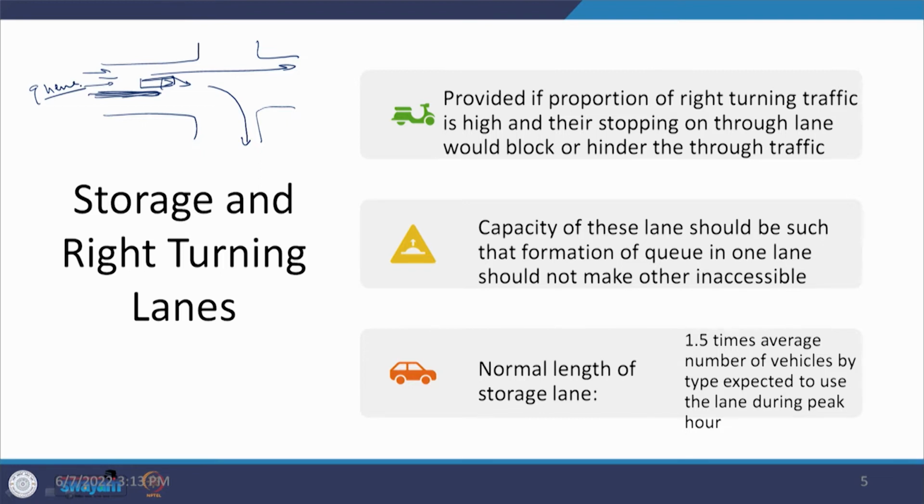and this is not good for the efficiency of this particular intersection. And this is the reason we need to look at what should be done so that this right turning traffic, when it stops here looking for an opportunity, because there is traffic coming in this direction also, does not create an impact here in terms of a conflict point. So, can we omit that? What type of design feature needs to be included? What type of changes need to be made in this intersection area?